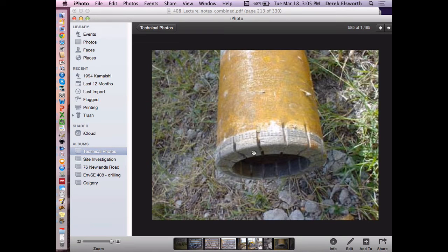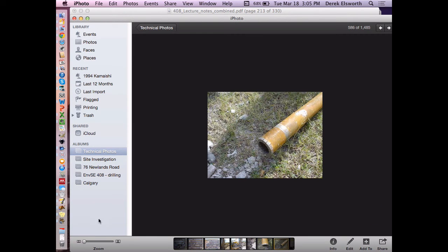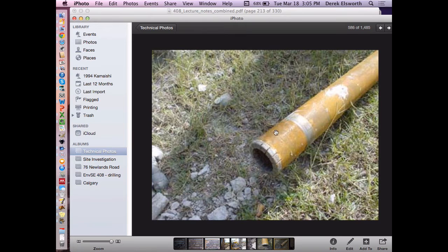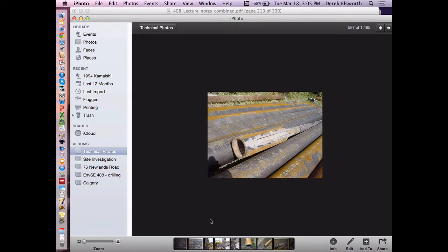And there are diamonds, you can't really see them, on the front part of this. These little bumps are all industrial diamonds, which make sure, of course, that the hole you drill is larger than the drill steel that follows, because you don't want the drill steel to get jammed in the hole. So the reason that these sit proud is to be able to do that. This little reamer is a row of industrial diamonds as well that also over-reams the hole, so that you don't end up with your drill steel stuck inside there.